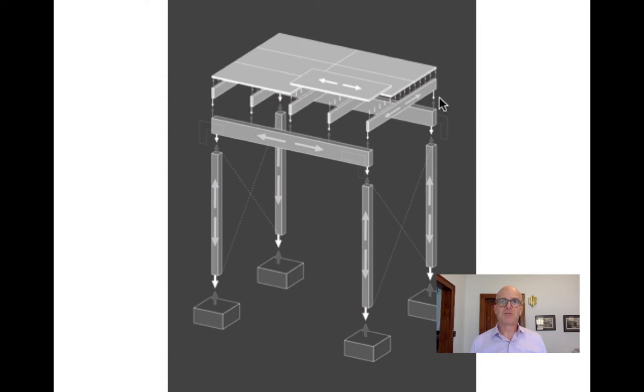So just to go through the process, we'll look at slabs first, go through again some of the charts that we use to size those, go back and look at the process for beam design, shear moment diagrams, the section modulus, steel tables in particular, and the iterative way that we figure in the dead load. Same applies for girders, and then we'll look at columns, slenderness ratios, the column tables, and then finally foundations, just the very simple load and area calculations and the soil tables that we use to figure those.